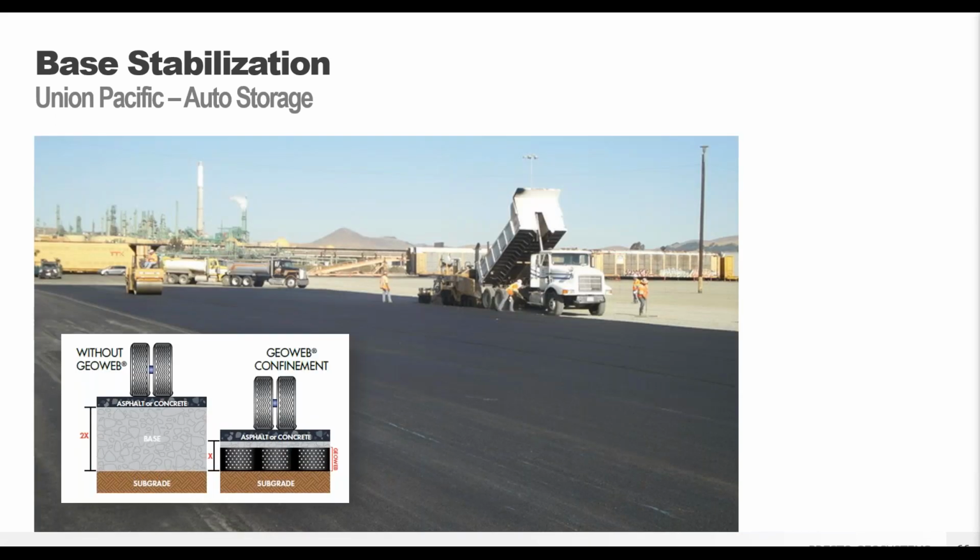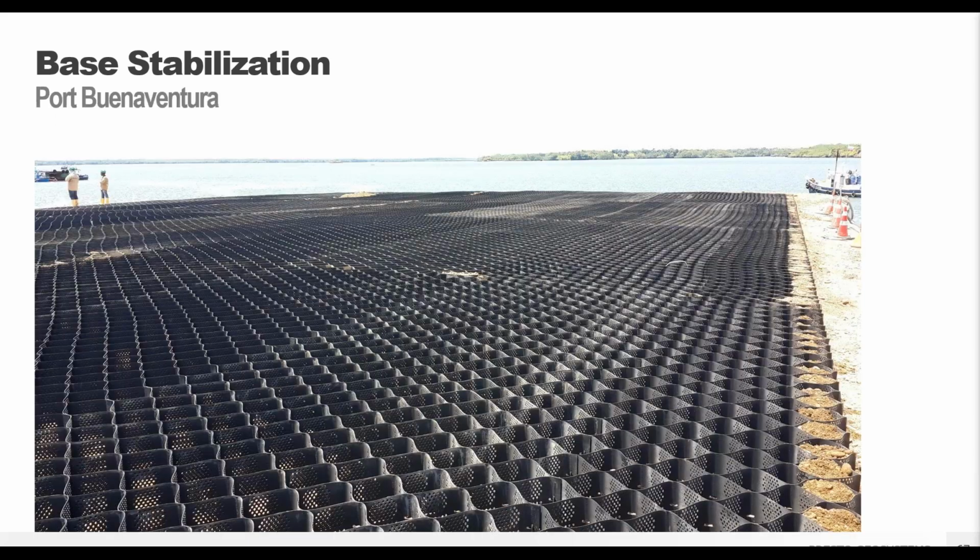And then they placed asphalt on top of the GeoWeb panels. So a regular asphalt paver was used. It was compacted with a standard smooth barrel roller. As I said, no special equipment, no special procedures are required when paving over the GeoWeb system. So your regular asphalt crew can install at their regular speed. They don't need extra training. They don't need to take it slow. They don't need to wait for cure times, anything like that.